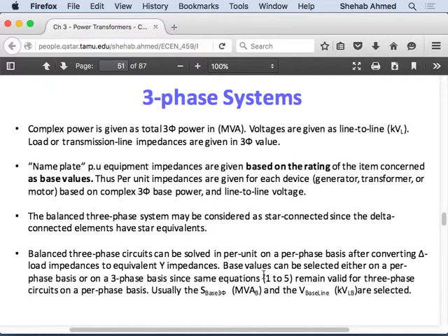It's for the full three-phase system, yeah. And the voltage base in a zone, you're asked to select 240 in the previous example. Here you will also be given voltage rating of equipment. The voltage base will typically be the line-to-line voltage base, right? So it's the line-to-line values that we will always be dealing with, right? Terminal values. The line-to-line values that we see is going to be the voltage base for a three-phase system, right?